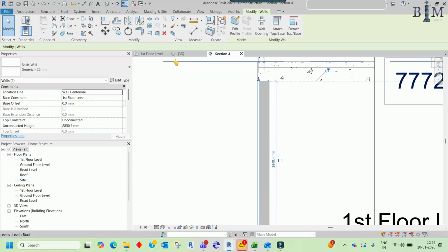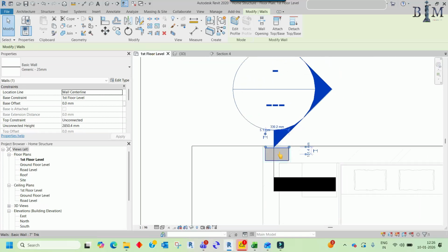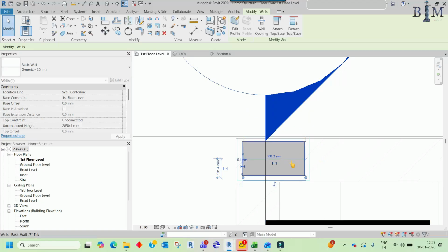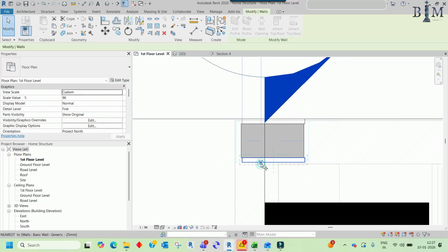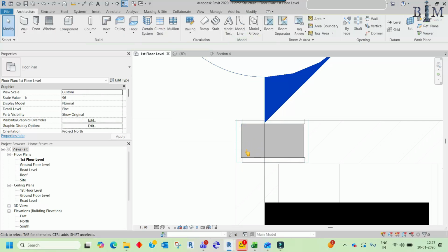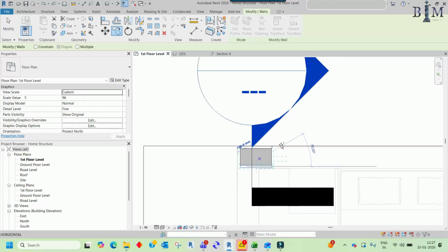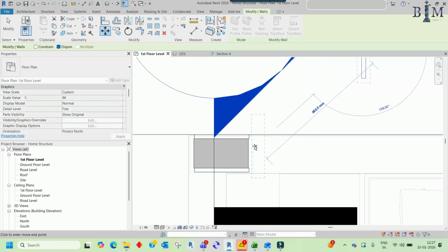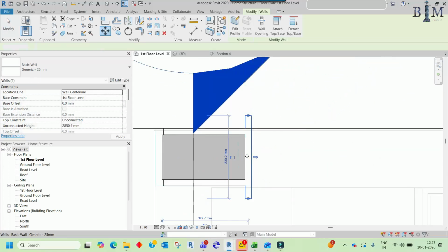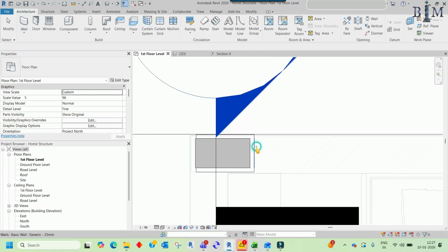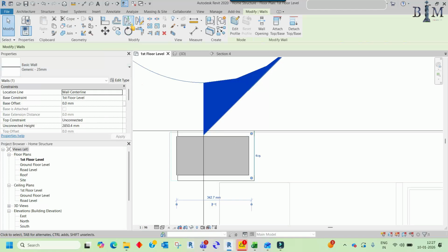For now, check in the plan, and mirror it, take the copy and mirror as per this axis. Now copy the element here. It is joining automatically with the structure. In that case, Ctrl Z and copy again, and keep it here, rotate 90 degrees, and move the element to this location. And now trim the corner.